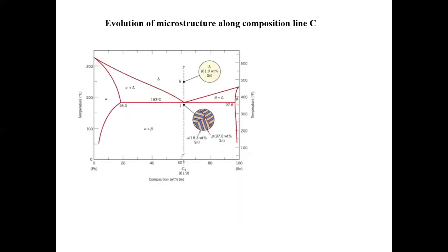So this is the eutectic transformation. And this is, again, another pathway for the solidification. So we will devote quite a few lectures to understand what the thermodynamics and kinetics are for this transformation as well. And as you can imagine, this eutectic transformation involves very interesting diffusion phenomena, right? To generate these kinds of lamellar structures. And we're going to discuss that in detail later.